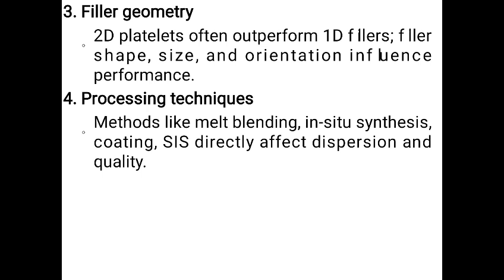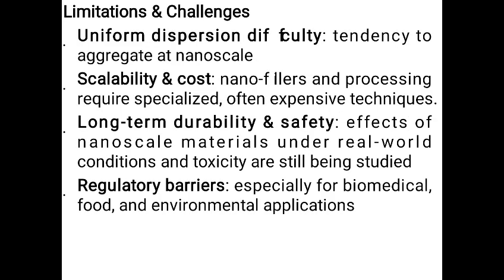Filler geometry: two-dimensional platelets often outperform one-dimensional fillers, and hence this filler shape, size and orientation are having a better role in improving the performance. Processing techniques: methods like melt blending, in situ synthesis, coating directly affect dispersion as well as the quality.